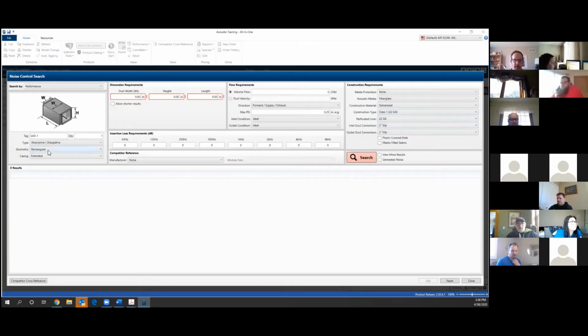So let's say you had a makeup air unit or a dedicated outside air unit on the roof. It was 20,000 CFM, and you were coming across, let's say, 40 by 24. We're going to allow it to pick a maximum length silencer. We can let it pick shorter, and we're going to have 20,000 CFM, and we're going to allow a pressure drop of 0.2.